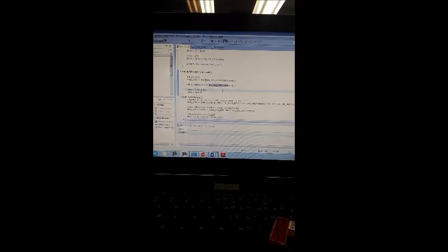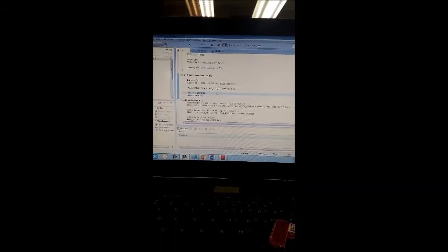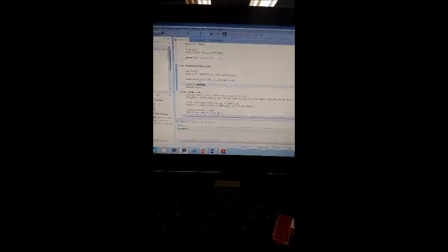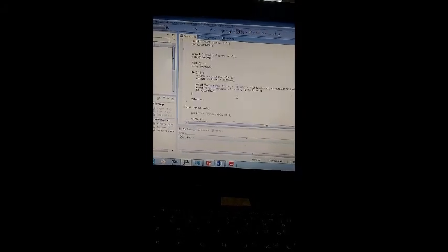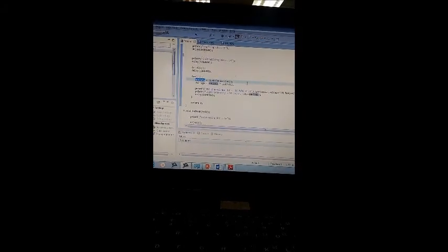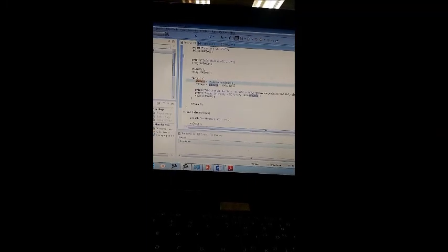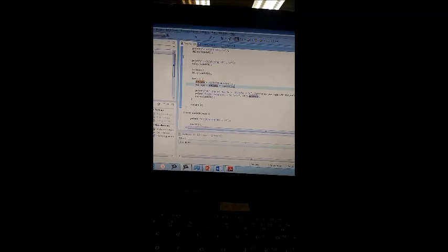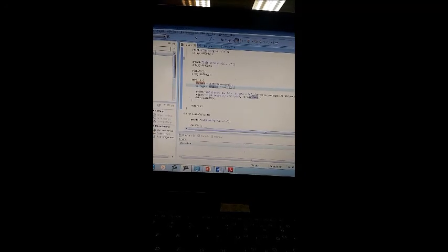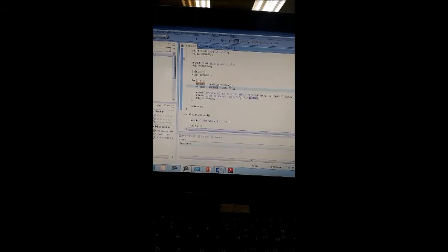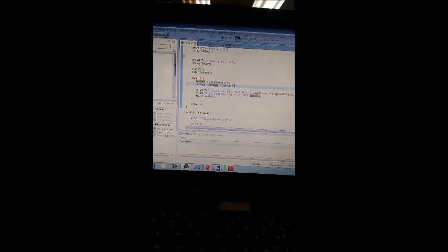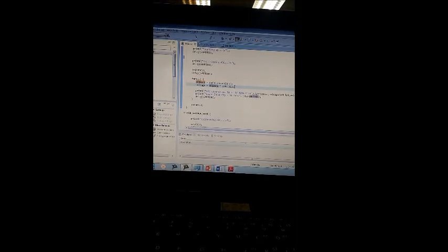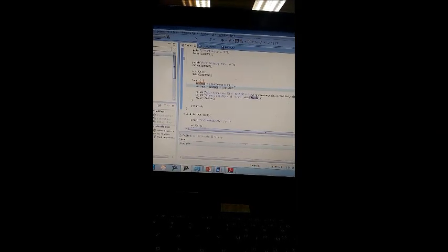After it completes, we save by using the ADC0_RA. We save the data into the result and pass it back to our main, saving at ADC data. So why do I do this conversion is because we set that the DIFF mode is 0 and we set the ADC mode to be hexadecimal 02.